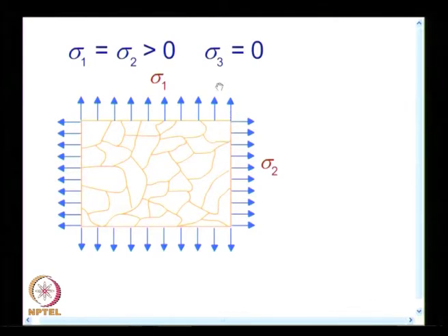So, if you come across random crack patterns in your buildings, if you watch the whitewash and you find that you have random crack patterns, you can immediately conclude that the principal stress direction is the same in every direction in this zone of the building. You can notice this if you go and watch your house very carefully, the whitewash that you have, because the building gets stressed and you can find out by looking at the crack patterns, and comment whether it is a uniaxial stress field or biaxial stress field or where sigma 1 equals sigma 2.